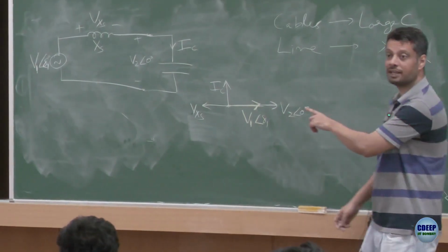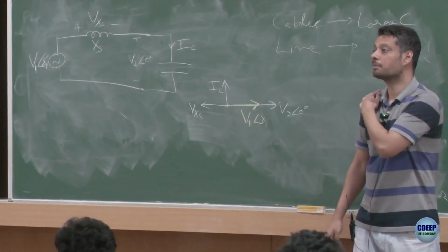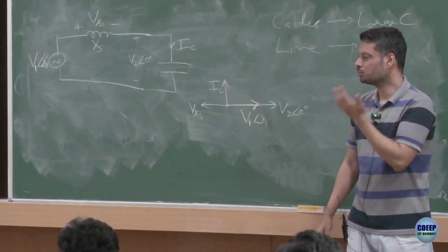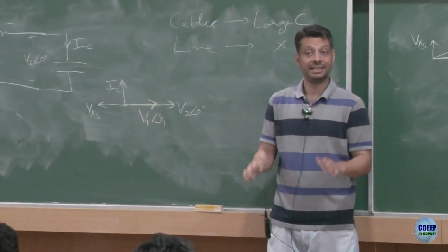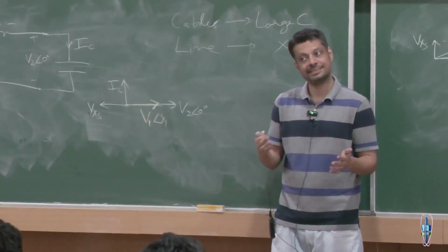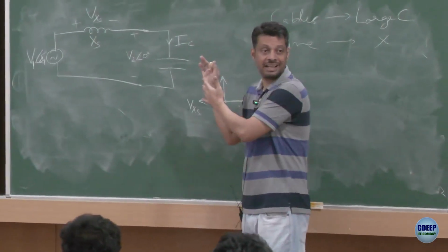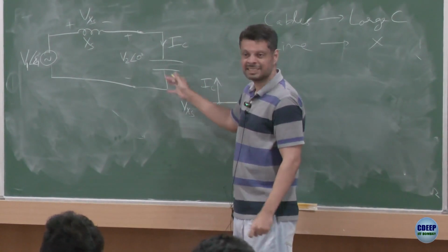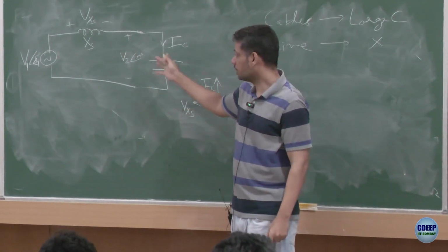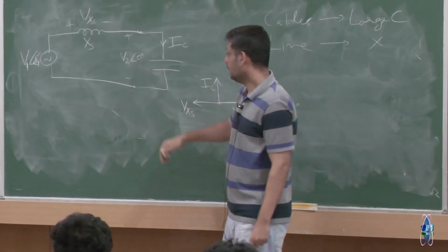Is this diagram okay? Anyone want to have a quick look at it, cross check if we have made some mistake here probably? It's a bit unusual. We don't expect it, at least in DC systems. In DC you would not imagine it, in AC it can happen. If you have a light load condition or a lot of capacitive kind of load, your voltages here could be very, very high, right?